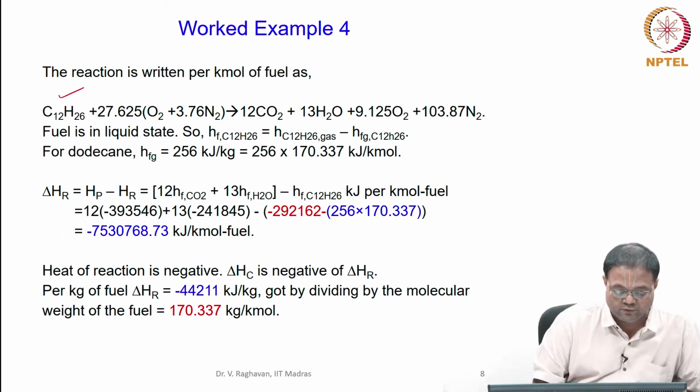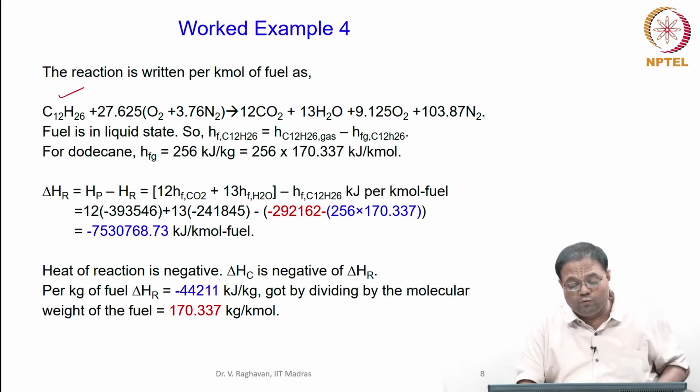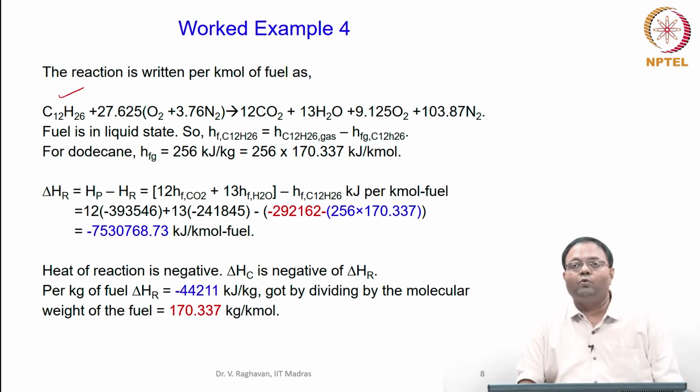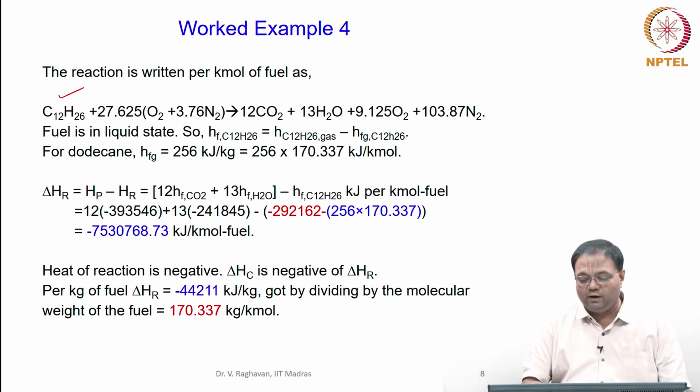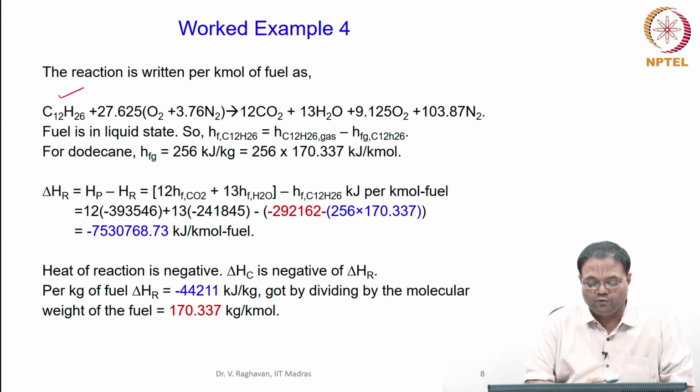So C12H26 plus 27.625 O2 plus 3.76 N2 giving 12 CO2, 13 H2O, 9.125 O2 plus 103.8 N2. So it's excess air, so that comes out in the product also. So fuel is in liquid state.